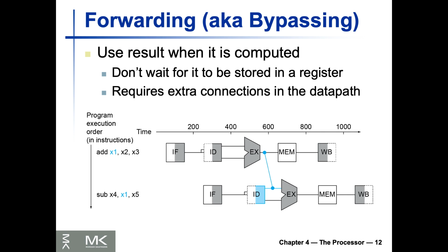In many of the recent hardware designs, there is another feature called forwarding or bypassing. In general, when you do an add instruction, after your execution stage, you actually have the result. You just wanted to write it to memory and then write it back. But at the same time, on the bus in your hardware, the results are available after X, so you could have used it right away. Instead of waiting for it to be placed here and then fetching it from here, you could just get another branch and ask, could you pass it to me at the same time? Could you forward the result you generated at your X stage right away, so at my ID I can use it, okay? So this feature in hardware is called forwarding.